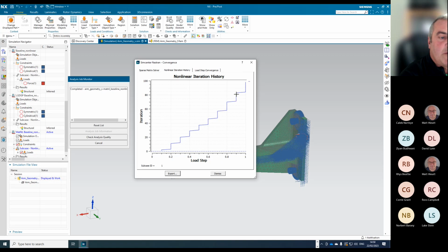At this point you've got parts of the structure where the material is nonlinear, therefore it has to work out what the stresses are on the nonlinear curve for the elements, and then achieve a convergence. So up until 0.6, it's still pretty much linear. But once we get past here, we can start to see where we're running in a nonlinear area for the material. Something else you can learn from the convergence curves.